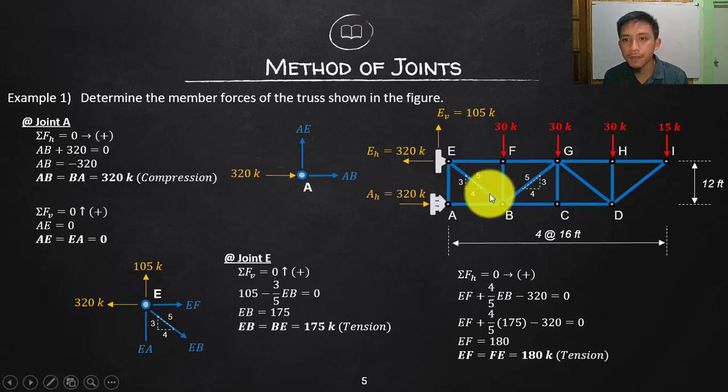First of course we need this, because later on we will represent the members as forces, and a force is an arrow with direction. For us to represent, for example, member AB, we will isolate each point, and that is what we are going to analyze. For example, I want to isolate joint C. I will isolate that one, and the three connected members, I will represent with arrows.